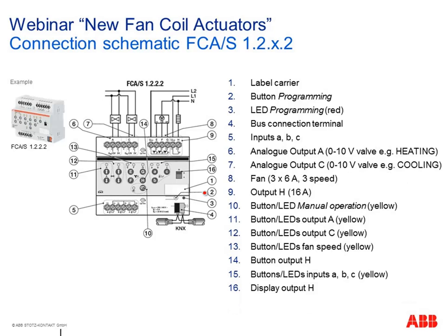And the next device with 0 to 10 volt is really not different. Only here you see 0 to 10 volt, 2 outputs left, because we need also here 2 connection terminals per signal, and so you can connect here 2 different valves via a 0 to 10 volt signal.